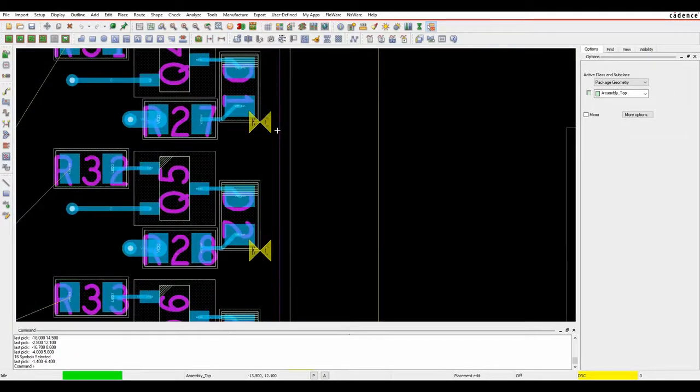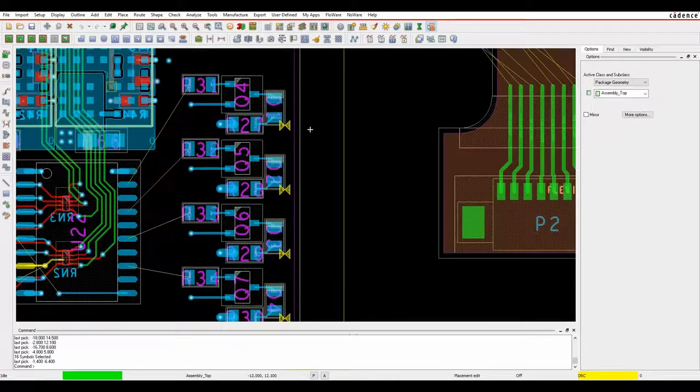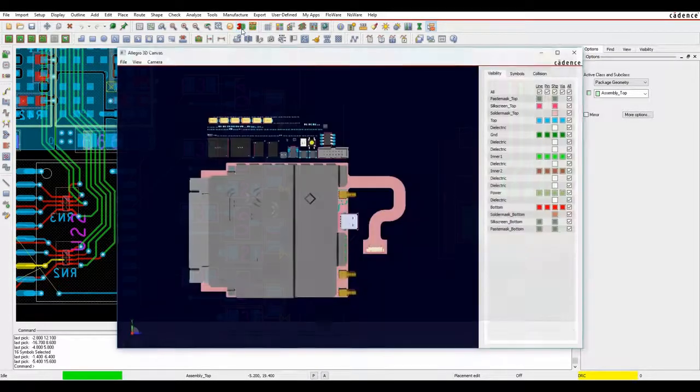So once complete, I'm zooming in, I'm getting a DRC error. It's a design rule check error. I've got an issue with placing of this module. So if I have a look and I'm going package to place, keep out spacing, the routing looks okay, I've got no component issue, so potentially I've got a 3D issue. What we'll do is we'll click on the 3D button to launch the 3D viewer.